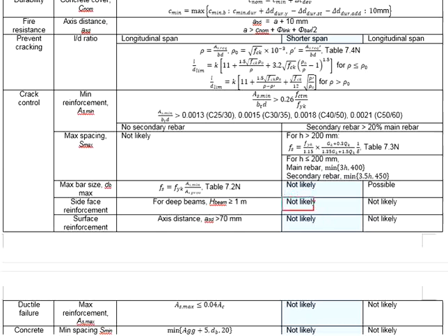As for the slab and the staircase, it is not likely an issue, as the depth of the staircase and the slab are normally not high, normally within 200 mm. To make it simple, side face reinforcement bar is not applicable for the slab and staircase. As for the beam, not all the beam require side face reinforcement. It is only required when the beam's height is more than 1 meter.